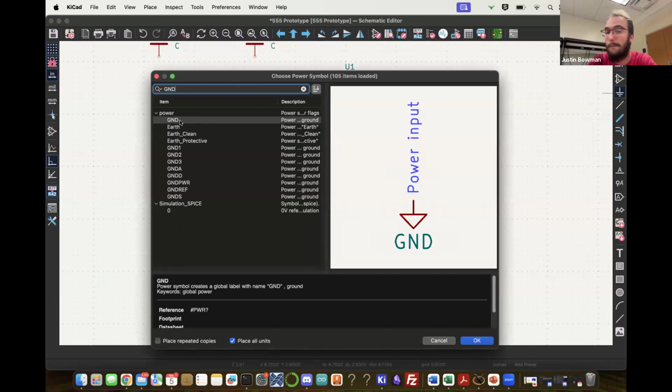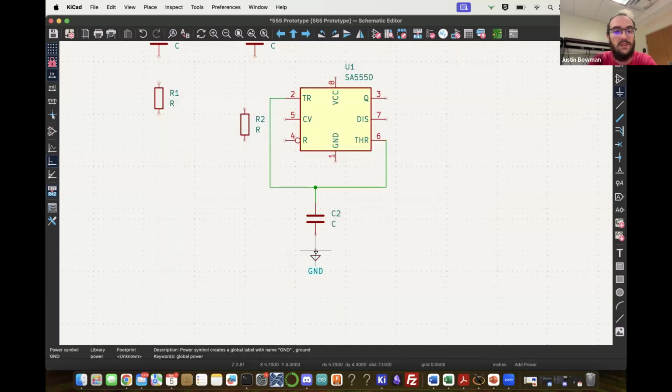Essentially, to add stuff, you just click on the circle and then click on the other thing. You can also click on the symbol below the power symbol, and that will be your add wire icon. And then the ground you added here.